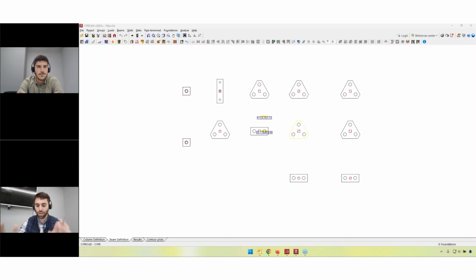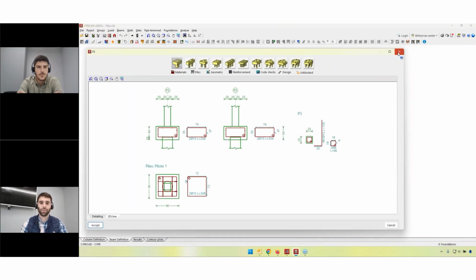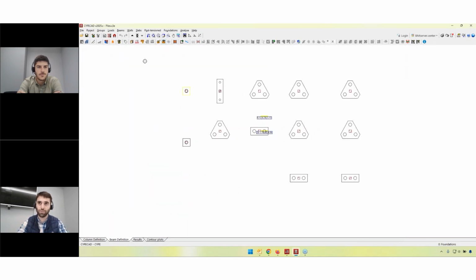So first of all, of course, we are doing the pile calculation, but this pile calculation has to do with a lot of, let's say, geomechanical formulas that are norm independent. So what do I mean by that? The shaft friction and the tip resistance are calculated with empirical formulas, and everything that is considered by the norm has to be also taken into account.